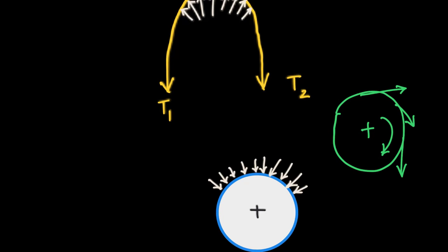Had there been friction, then there would be some tangential force acting at these points, which will cause the pulley to move. Make sense? So next time when you hear the word frictionless pulley, you need to appreciate the fact that the pulley won't be in motion. The pulley won't know what happens over it because there is no friction, there is no tangential force. Make sense?